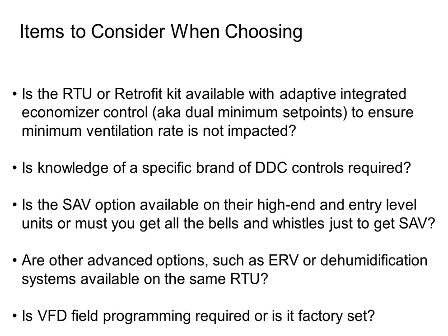Sometimes also, if you do staged air volume with certain manufacturers' equipment, it prohibits you from using other accessories because they don't have the control ability to handle that. So sometimes they won't let you do staged air volume plus an ERV, or staged air volume plus a dehumidification system like hot gas reheat. Sometimes you can only do one or the other. So you guys have to pay attention to that too when you're designing your system out.